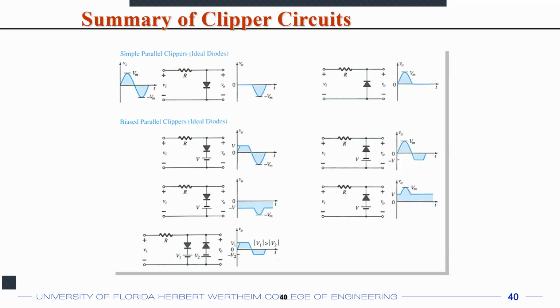The current is very small because I'm not conducting as much, but the voltage that I'm storing could be very high. And it can instantaneously get passed through the electronic circuit and damage it. And that is the reason why electrostatic discharge or ESD protection circuits are required. These are also called surge protection circuits sometimes. And what you'll see is that they will be designed using these two back-to-back diodes, something like this. You may or may not have biasing in the ESD protection circuit. You may choose to have biasing.